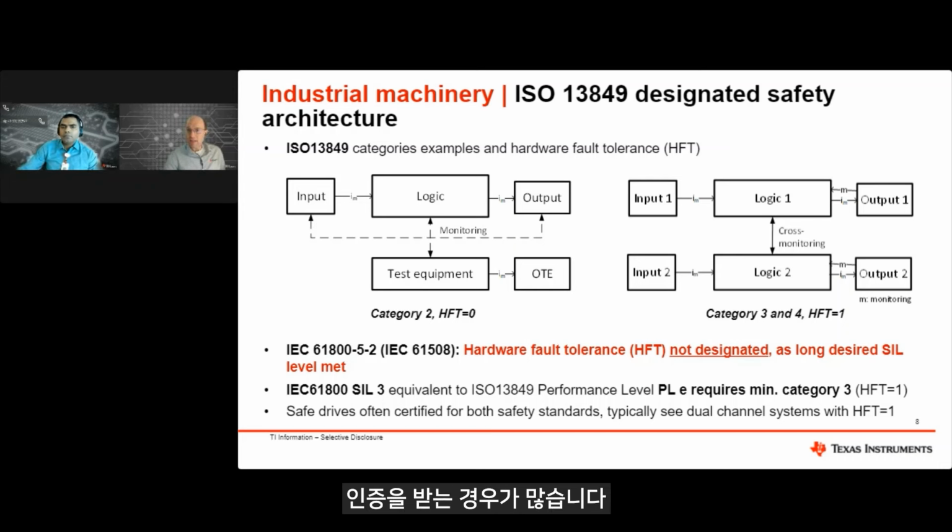Now let's have a look at the most important criterion, the fault exclusion. We want to exclude a fault which is a short across the isolation. This can be excluded if 2 items are met. The signal isolation component, the isolation, needs to be built in accordance with overvoltage category 3, according to the IEC 61800-5-2. The second requirement is that measures have to be taken to ensure internal failure of the signal isolation component cannot result in excessive temperature of its isolation material.